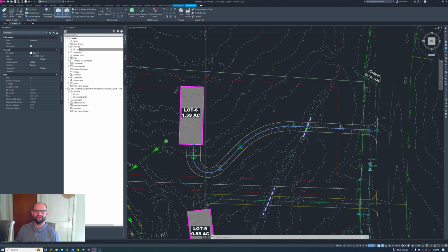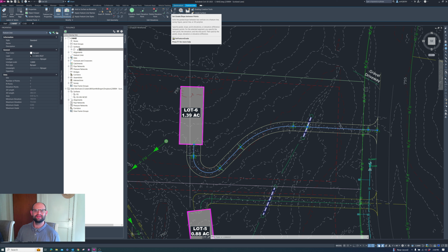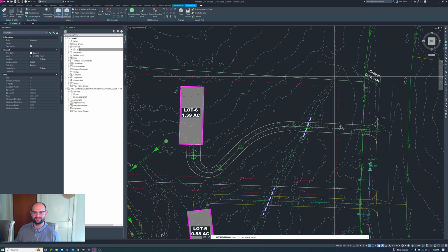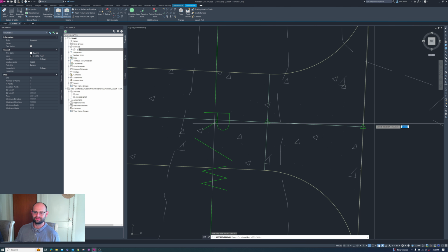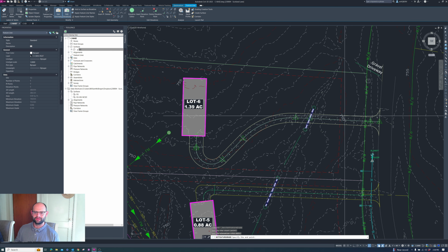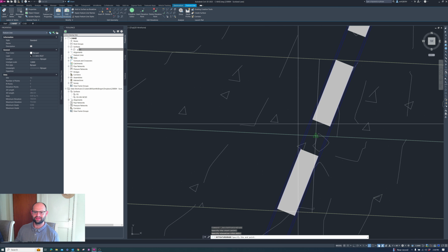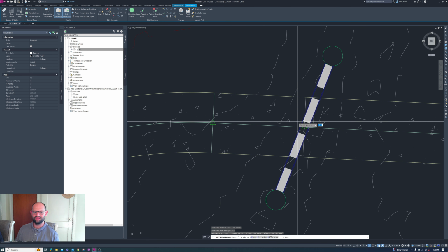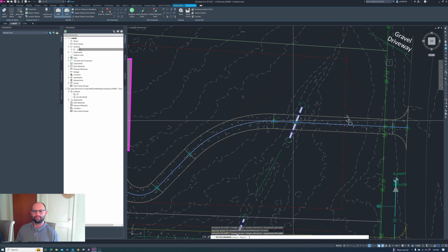We're going to use another feature line button command. One up here that looks like a little triangle. It says set grade slope between points. Click it. We're going to go to this point, click. We have that elevation set, so we're just going to accept it as it was. And then we're going to drag 3 vertexes over to this low point, click again, and that's going to set a smooth slope between those 2 points. Perfect.